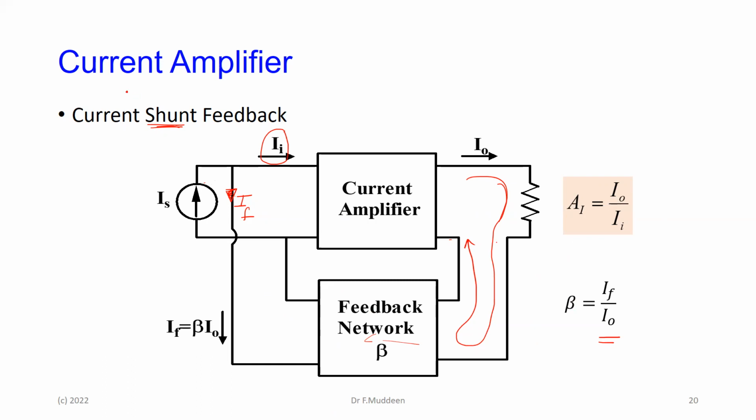Because it's current, and because the current source is modeled as a Norton, which is a source in parallel, you have to have, again, the feedback in parallel with it, such that Is is equal to IF plus In. Therefore, In is equal to Is minus If. Again, your negative feedback. Yeah?